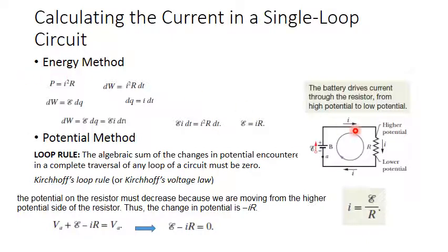From the point of view of energy, we say that the dissipated power at the resistance equals I squared multiplied by R. And this power, if it is integrated with respect to time, will be energy or work. So the delta W in the resistance at delta t of time would be I squared R multiplied by delta t.